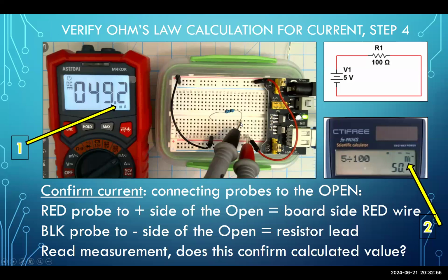If you put this black probe over here to the wrong end of the resistor, you'll blow the fuse for sure. Okay, so I'm describing that. I'm not using the probe tip as a pointer where not to connect. I'm just telling you now, this probe tip has to be on this side. This is where the open is.